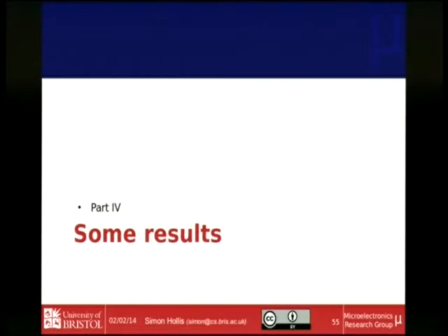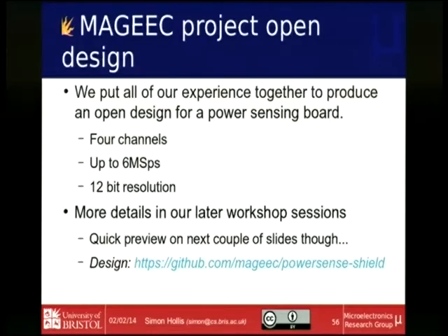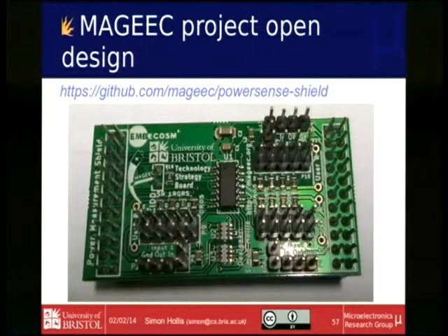And I have, I think, 1 minute left to just show you what these designs look like when you scale. If you want to play more with these designs, you have a workshop session, you can come and you can take them home. So we've got this device, and it's an open source design. Here's the link, you can download it. We use open source CAD software, and you can download the design from the CAD software, generate files and send them out. 4 channels, 6 megasamples per second, so it would measure accurately everything we've seen today. 12 bits resolution, and this is what it looks like.